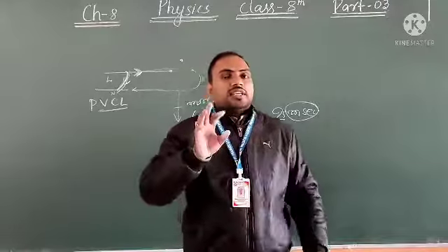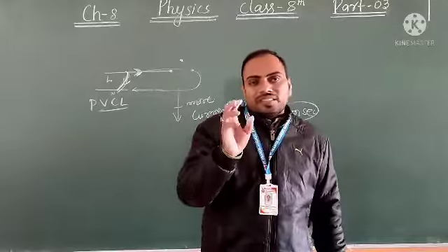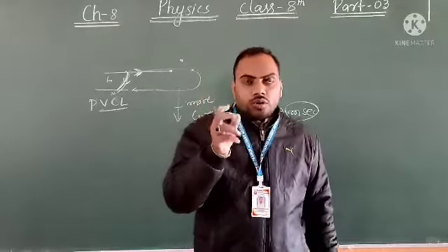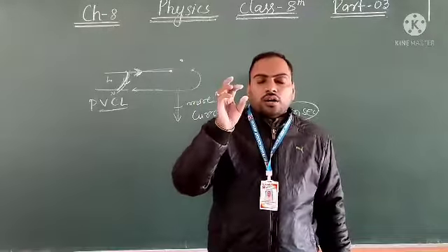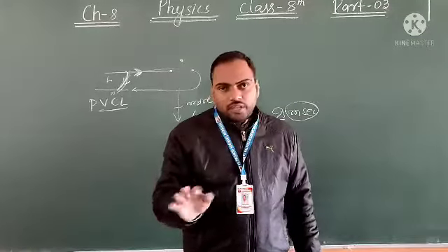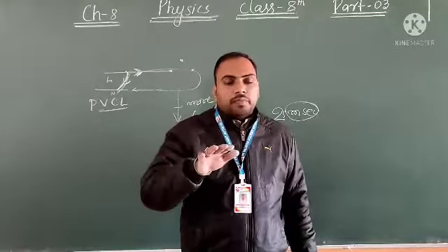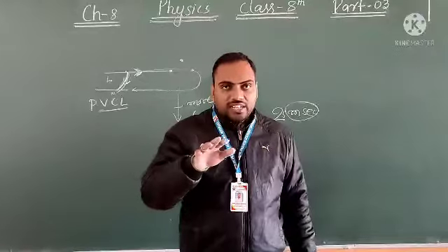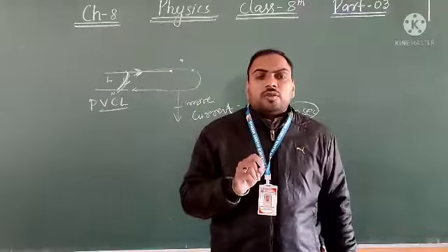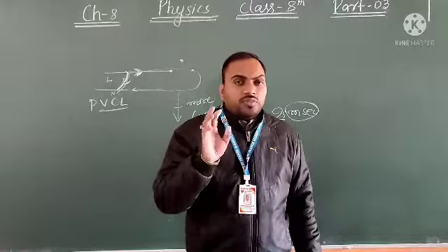Precautions. There are some main precautions you have to take while dealing with electricity. If you want to change or replace the holder, socket holder or bulb, do not come in contact with the earth. Be on a wooden platform, on a plastic chair, and then change it. Another thing to keep in mind while doing these activities: your hand should not be wet.